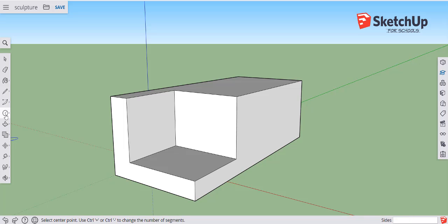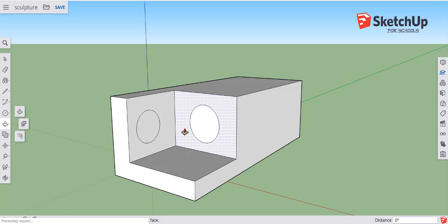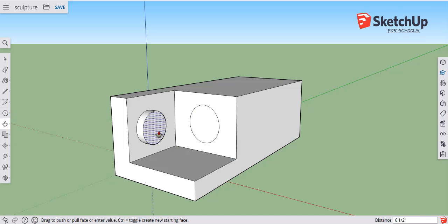For example, this time when we select the Shape tool, click on the circle. Draw a circle on one of your surfaces. Simply click to start, pull out the radius, and click again to finish. Now draw a few more circles on the various surfaces to see how the orientation aligns with the surface you're drawing on. Use the Push-Pull tool to create some cylinders.